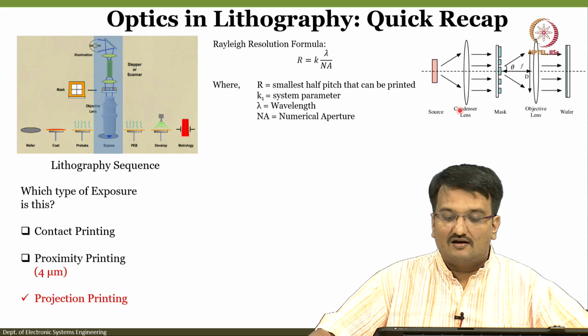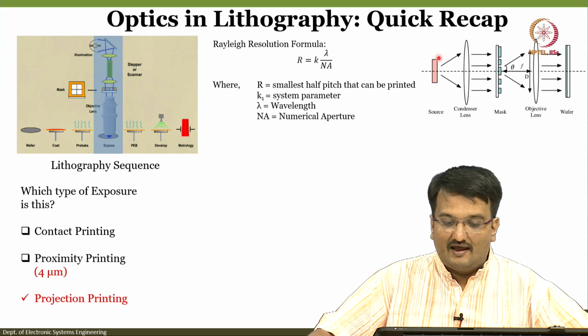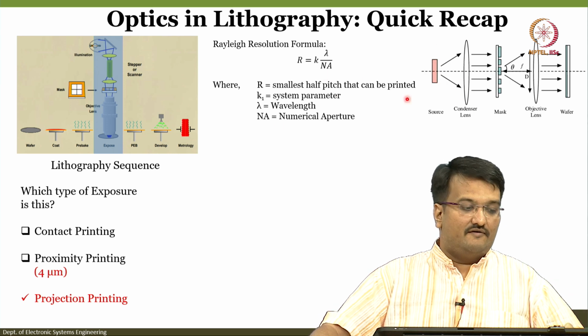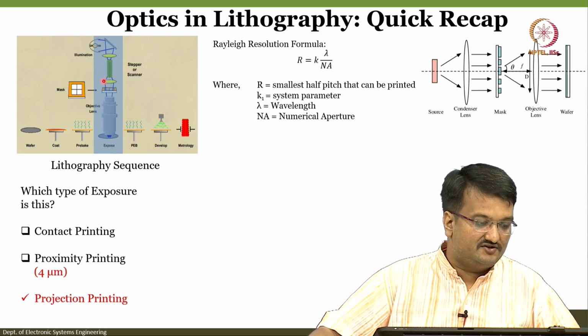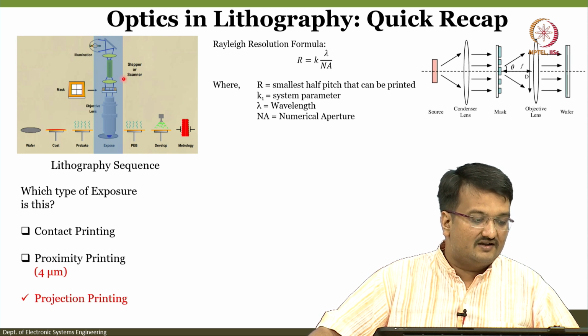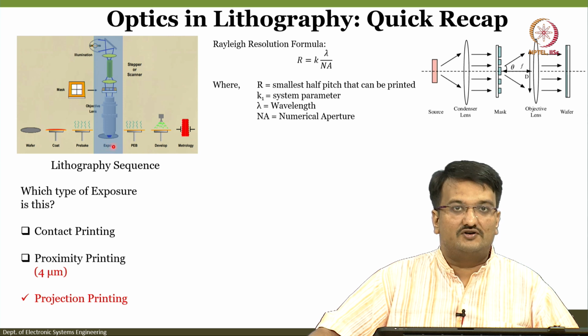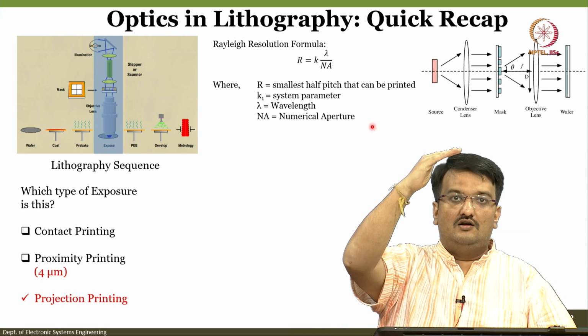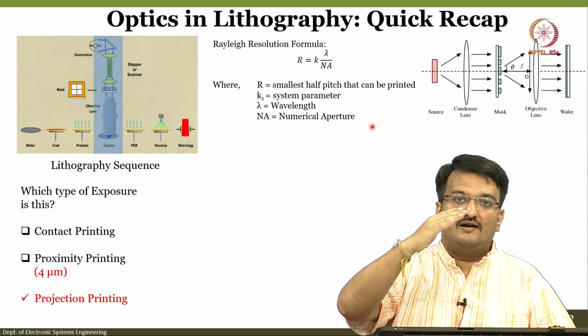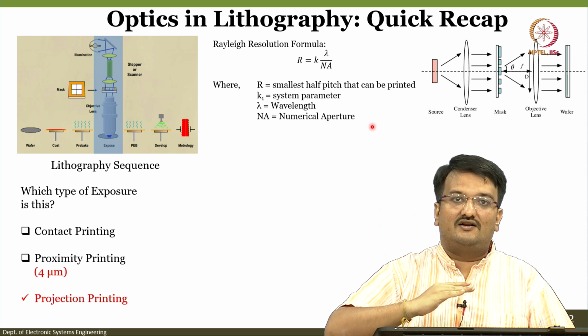Further, this is a diagram. What I like about this is, if you see here, the lithography sub process starts from illumination, condenser lenses, mask, objective lenses and your exposure. In the same way, this is illumination, your condenser lens, mask, objective lens and wafer.